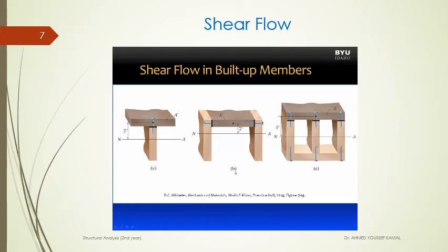Beam B is composed of 3 parts, and we can see that there are 2 fasteners at a given cross-section, and we can calculate the shear flow on both of those fasteners. Considering the Q equation, we would use for our A prime area the shaded area here. The y bar prime would be the distance from the neutral axis to the centroid of A prime.